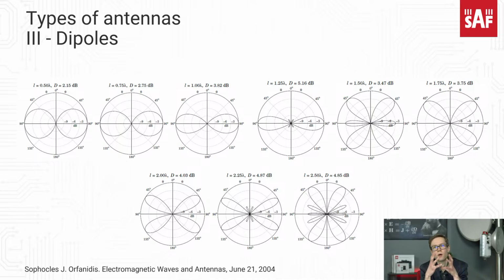The side lobes become more evident, and the direction of these lobes changes. You can see now there are 4 more main lobes in 4 directions. And this transformation continues until we obtain very exotic radiation patterns of multiple wavelength dipole antennas.